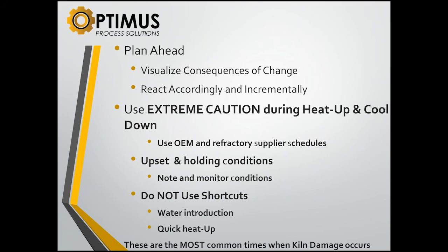What can happen in a situation is that if you do put uncontrolled water into the feed end of the kiln, you may get into a situation where that water works its way down, goes through a buildup, and rushes down into the burning zone. Here you have hot, partially or completely calcined lime, which is then going to react with that water. You can get into issues as bad as steam explosions occurring, and you can't get out of the way fast enough. Quick heat ups are bad because they're difficult on the equipment overall, and especially the refractory.